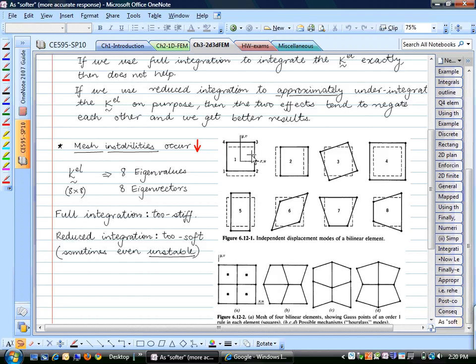So that means that the pure deformational mode is linear for this element, and the only rigid body mode in one dimension was translation in one dimension. So for the midterm question that I asked you, if you assemble this into a truss element in 2 dimensions and 3 dimensions, if I assemble a truss element in 2 dimensions, you would get a 4 cross 4, out of which 3 eigenvalues would be 0.